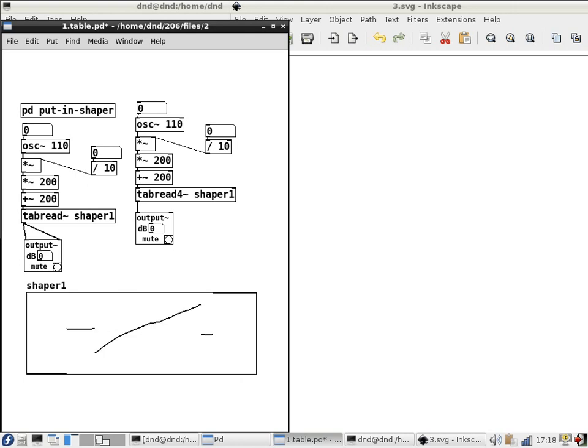The good thing about the function table is that it takes a reasonable amount of compute time. That's to say, depending on what kind of interpolation style you want, it might just be looking up a pre-stored point in a function, or it might be doing that and then some algebra to do interpolation. If you do the expression, it could be as much computation as it takes to calculate the expression. So the table is really a way of pre-calculating the expression.